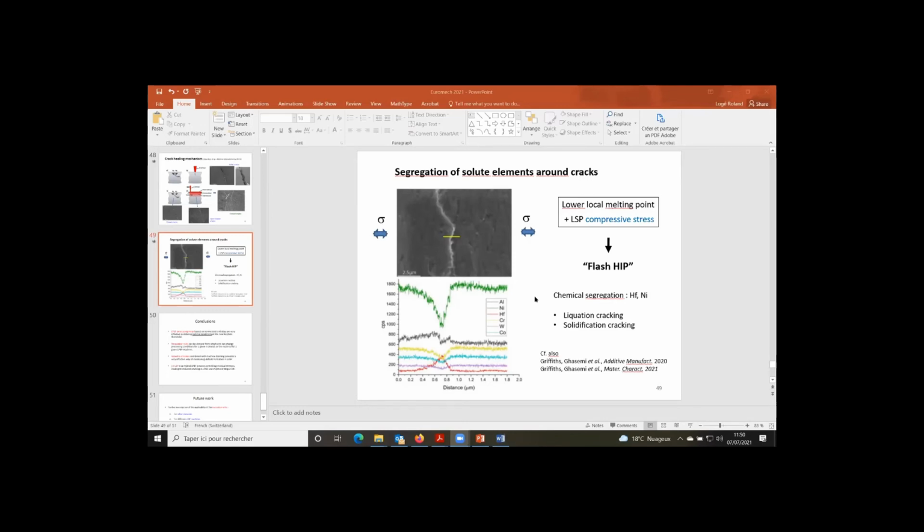That's why we usually like to have a beam size of typically a millimeter, such that it penetrates up to 1 millimeter, as I said. Now, if you use those faster lasers, it's just more expensive in terms of processing time, because instead of doing that every 10 layers, for example, you would do that every single layer. But it's a possibility, yeah.